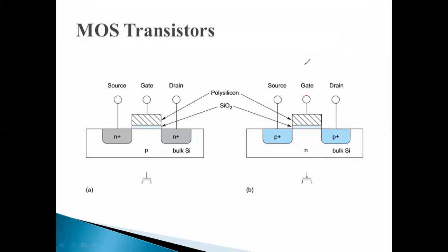So in digital level abstraction, NMOS transistor turns on when the gate input given to it is logic 1, and NMOS transistor turns off when its gate input is equal to 0. Similarly, PMOS transistor turns on when its gate input is 0, and PMOS transistor turns off when its gate input is made as 1.